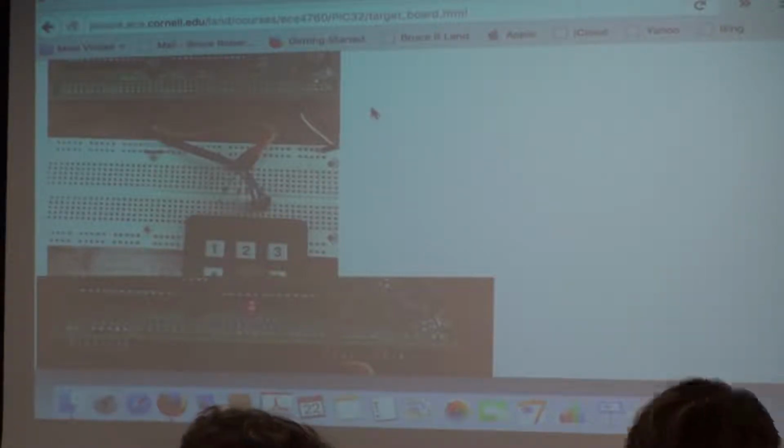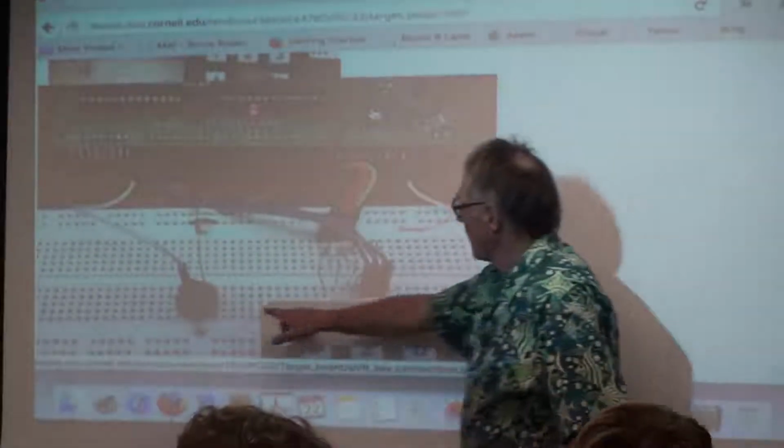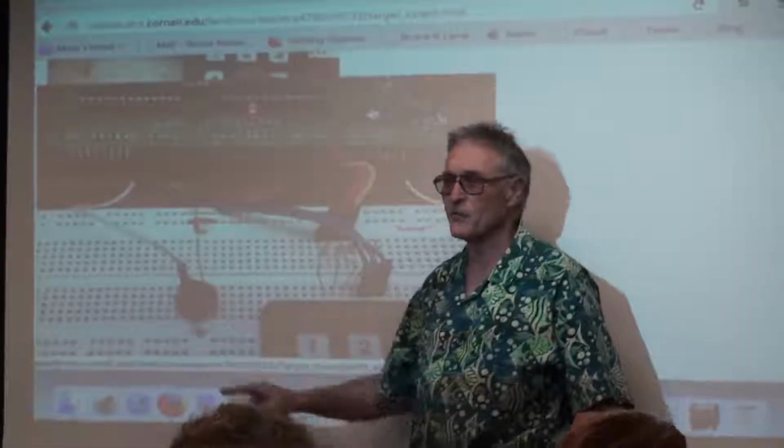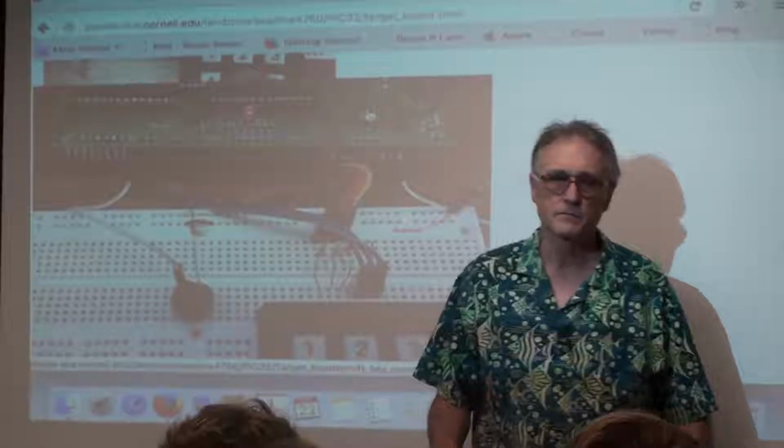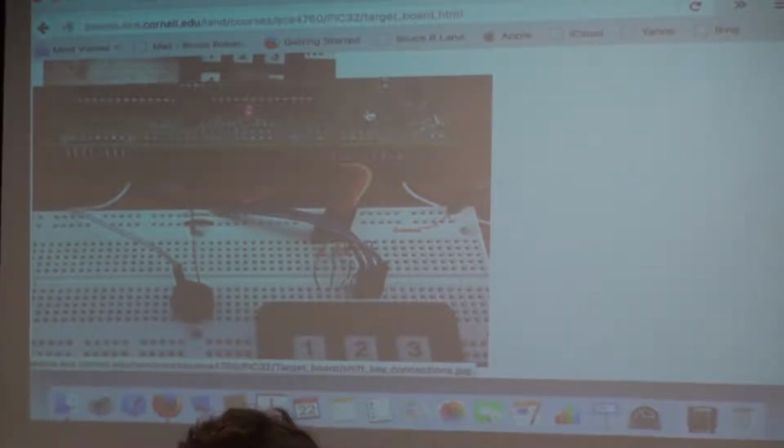In this case, the keypad is connected to port Y, and the second example connected to port Y with a shift key. So now you have 24 button pushes possible rather than 12. I used one 8-bit port to implement a 12 key keypad plus a shift key.